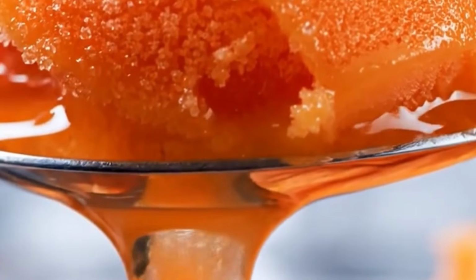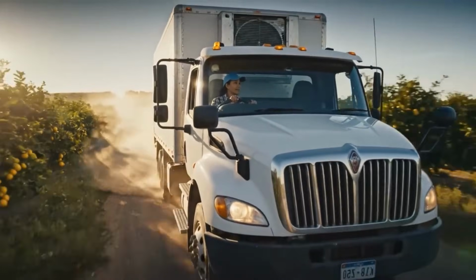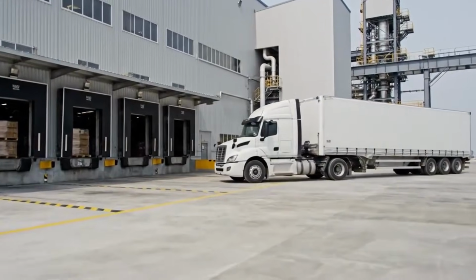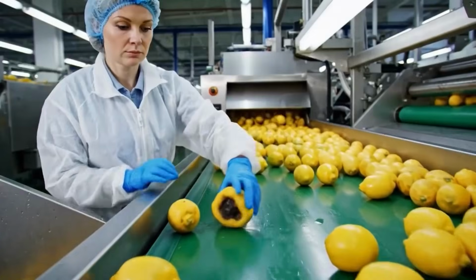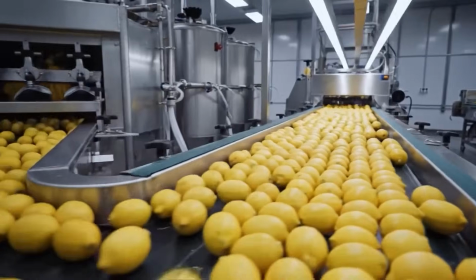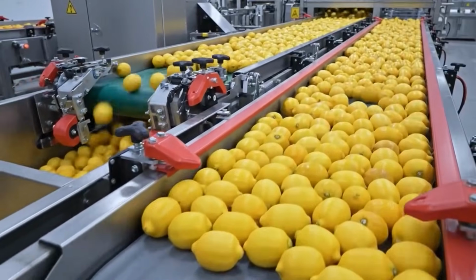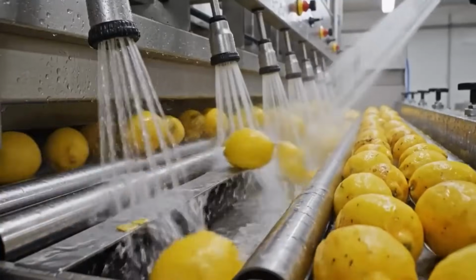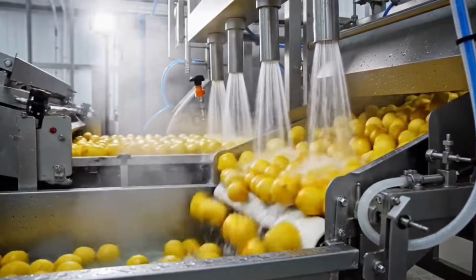Each batch of sorbet is traceable through electronic production records, linking ingredient lots, formulation parameters, processing times, and packaging data. Digital records include metrics for pasteurization, Brix values, overrun, pH, freezing rate, fill weight, inclusion density, and packaging inspection results.